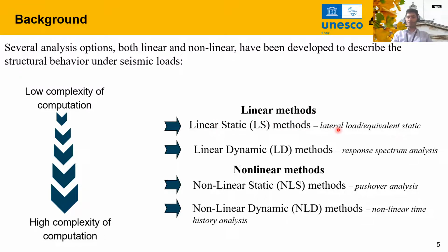For example, the linear static methods, lateral load or equivalent static procedure in the codes, the linear dynamic method is more reliable than the linear static, because here we at least consider the dynamic behavior of the earthquake, dynamic nature of earthquake, which an example is response spectrum analysis. Now we move on to nonlinear methods, where we could have nonlinear static methods, which Pushover analysis is an example, and nonlinear dynamic methods, where the nonlinear time history analysis is the example.